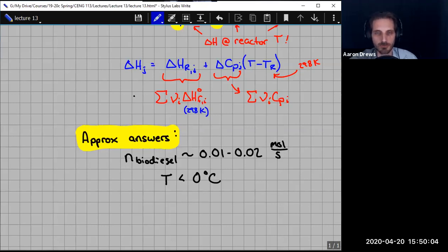And so we're absorbing a lot of energy in order to make these reactions go. That energy comes from somewhere. It's actually coming from the enthalpy of the inlet stream because the system is adiabatic. It's adiabatic, which is very easily accomplished just by wrapping the thing in a bunch of insulation. So we can't draw in energy from the atmosphere. We don't have any jacketed stuff on it yet because we're just dealing with adiabatic. So the whole thing is actually cooling. And it gets so cold that it's actually a problem because things will freeze. But that's as far as we got.